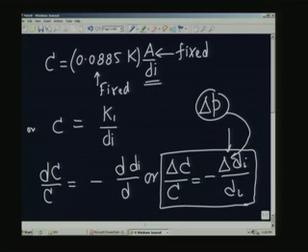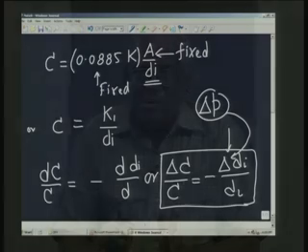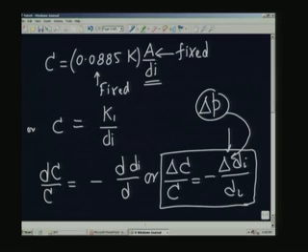In the diaphragm gauge, the diaphragm is going to undergo a change in shape, and the magnitude of the deflection is proportional to the pressure difference across the diaphragm. Essentially, what we are doing is measuring the change in the capacitance and relating it to the change in the pressure, or the difference in the pressure. Let us look at a few typical numbers.